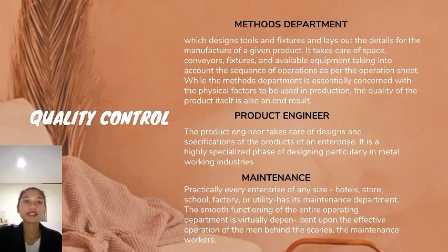So the last is maintenance. Periodic inspections, alignment adjustment, sharpening of production tools, lubrication of moving parts, and inspection of the machine to look for any issues are used in all parts of machinery maintenance.